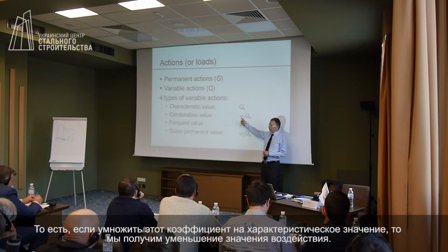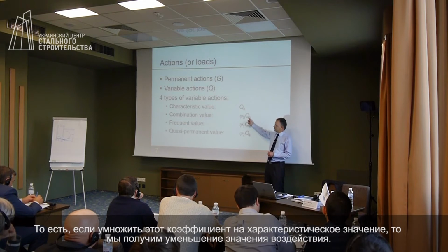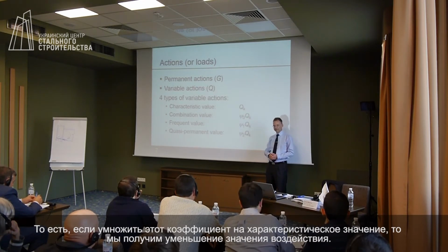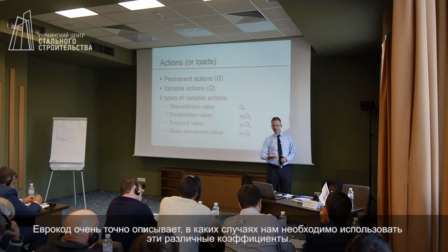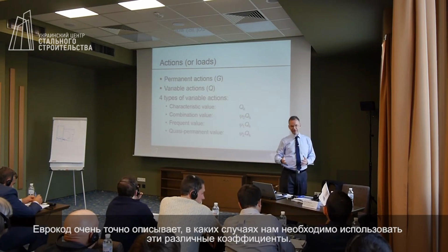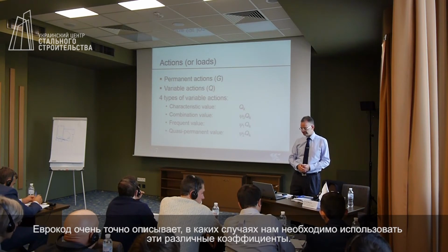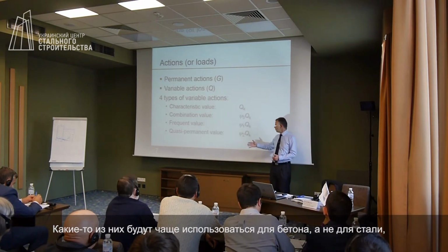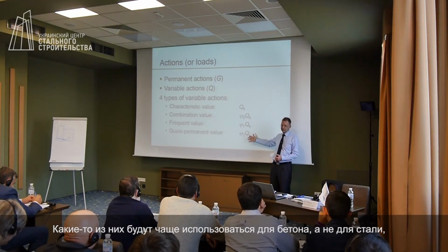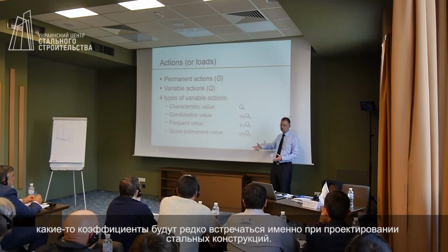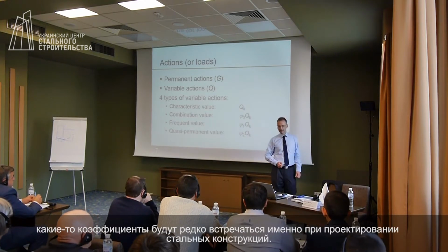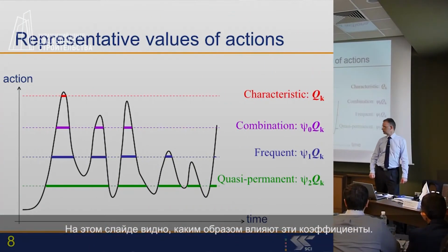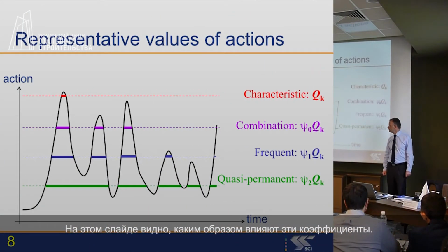So the product of this value and the variable action will be a reduced value of action. And the Eurocode is going to tell us precisely when to use those different values. Some of these will be more for concrete than for steel. So some of these hardly ever appear in our steel world. This is what the reduction factors do.